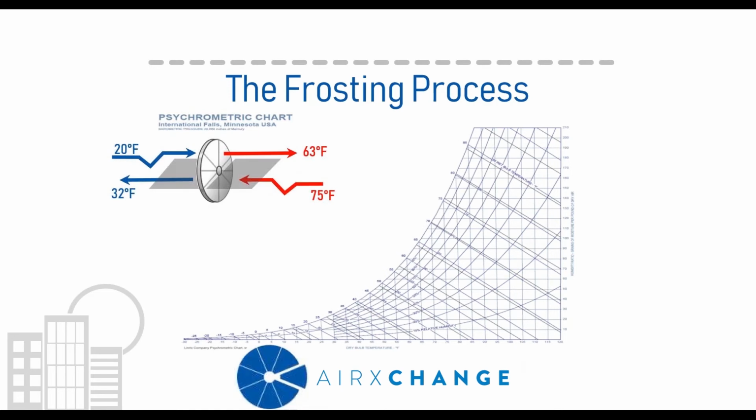Okay, so borrowing from our previous slide, let's plot that process on the psychrometric chart. Our outside air is 20 degrees. You can see it on the chart right over here. And our exhaust air is going to be 75 degrees. Now let's draw a line between these 2 points. This line represents the energy recovery process line.